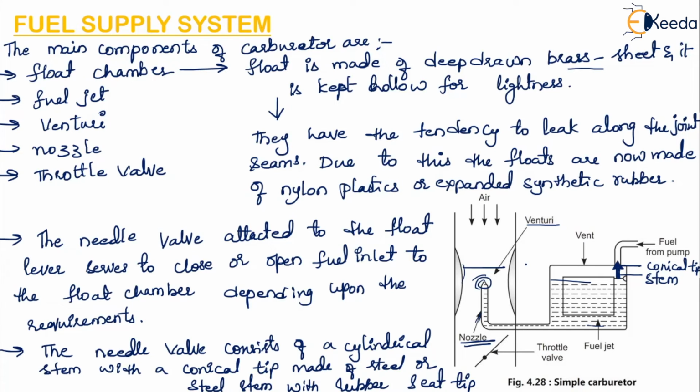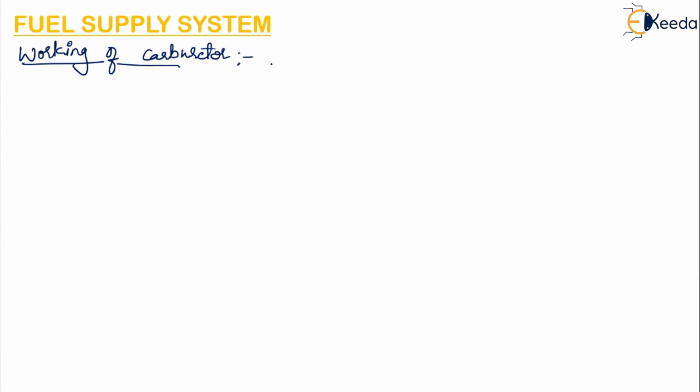As the fuel and air pass through the venturi, the fuel will get vaporized and the required uniform mixture is supplied to the engine. The important thing to remember is that the pressure difference between the fuel surface in the fuel tank and the pressure at the nozzle causes the fuel to flow into the air stream.